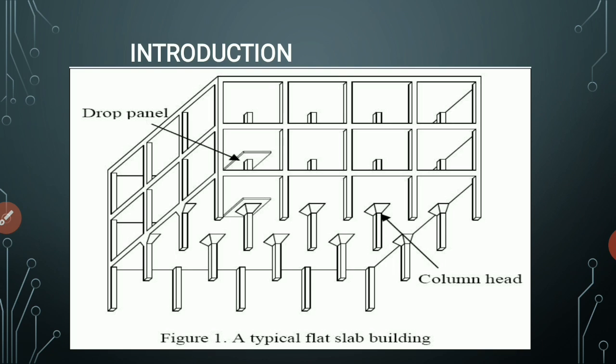A flat slab is a very complex structure and it is extremely difficult to determine the location and magnitude of stresses in the slab. Why is it so difficult? Just imagine a beam column junction. There we can calculate. We assume that at the ends of the beam we can have a diagonal shear, and at the center of the beam we have maximum bending moment. So we can identify those spots and those magnitudes for the standard cases.